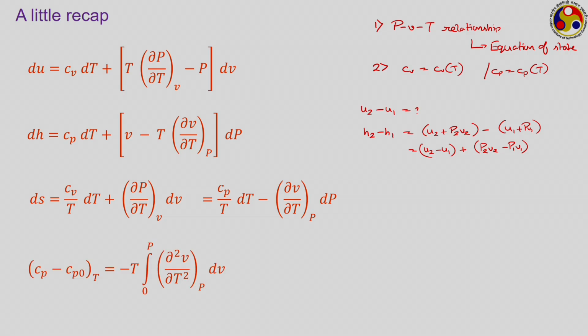And if we want to know how Cp and Cv vary with temperature, then this is an example of the relation of Cp with temperature. So, from the knowledge of again just the PVT relationship, we can easily calculate Cp as a function of temperature. And say if we want to perform one simple analysis, say for an ideal gas, to calculate the expression for Cv.